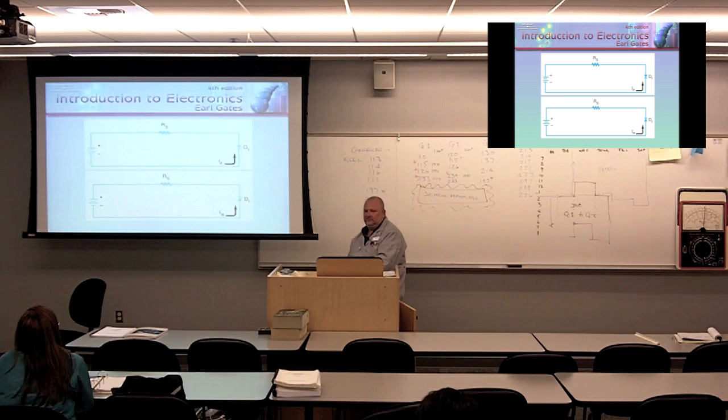How much current? Just a little bit of current. What kind of current? Reverse current, leakage current. So realistically, is there really any current flowing in the circuit when it's reverse biased? No, that's why it's reverse biased. We're using the diode to prevent current from flowing in the circuit. That's why we put a diode in it.